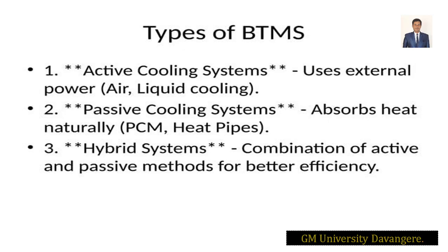So with liquid cooling, when you manufacture your cells, for example, you take cells which are connected in series and parallel combinations. Beside the cells, you should have a proper channel for the cooling effect, right? If you design it in such a way, we can pass any liquid or fluid to cool each cell when the temperature rises. So that is external cooling, and that is called active cooling.